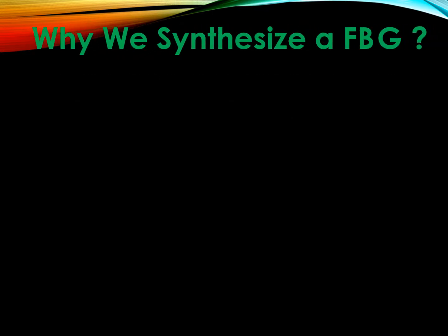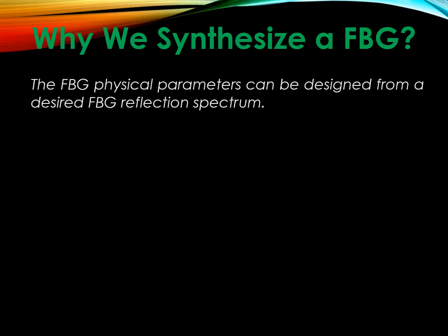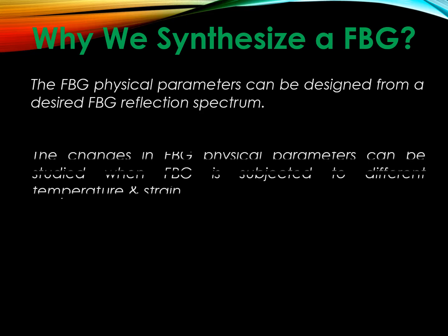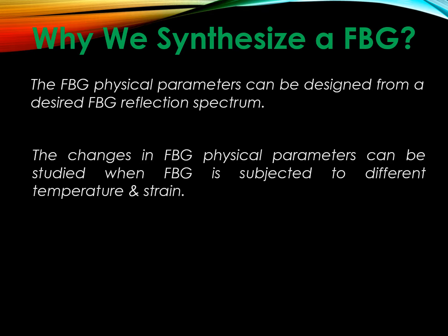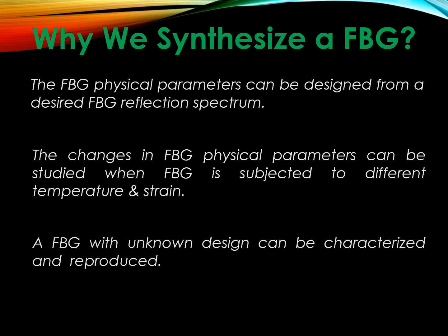Why do we synthesize an FBG? The FBG physical parameters can be designed from a desired FBG reflection spectrum. The changes in FBG physical parameters can be studied when the FBG is subjected to different temperature and strain. An FBG with unknown design can be characterized and reproduced.